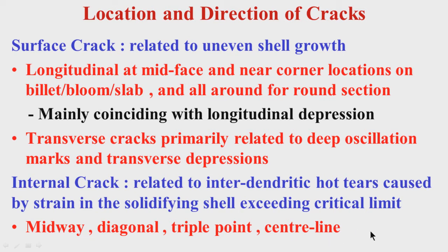I have mentioned how center line defects, segregation, shrinkage cracks, or too much porosity can be controlled to some extent by using mechanical soft reduction. It has to be of a certain intensity, and the location where you apply the reduction is very important. It cannot be just anywhere; it has to be near the end of the solidification zone, during final solidification.